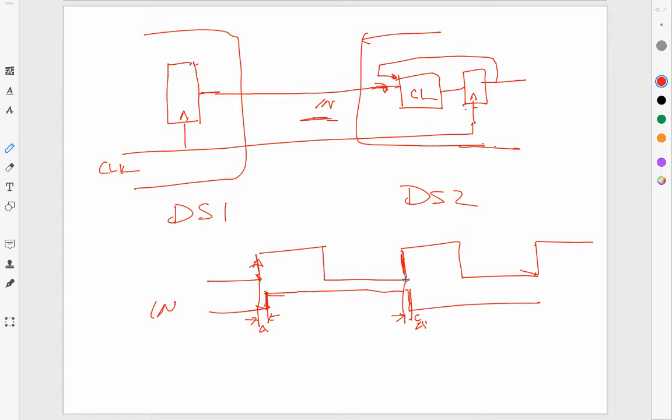So this is one design, but let's imagine there was another signal out here, which took some other bit, went through a combinational logic, and there is a second signal, and let's call it in prime. And let's say this combinational logic has a lot of delay. So if I were to look at in prime, it may change much later, because this long delay may come from this combinational logic.